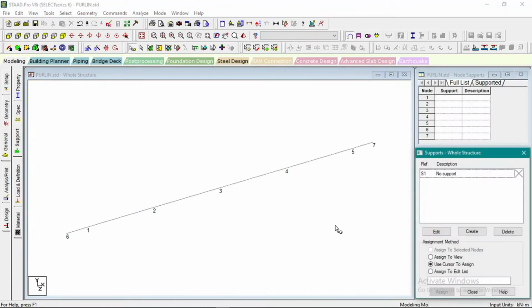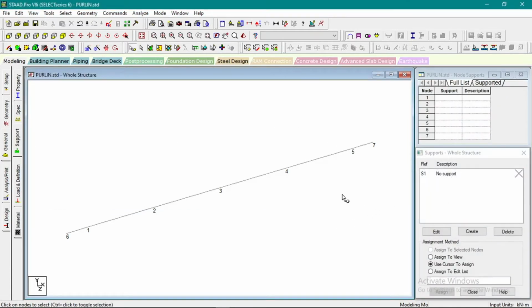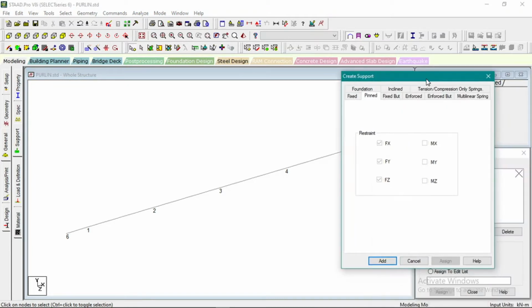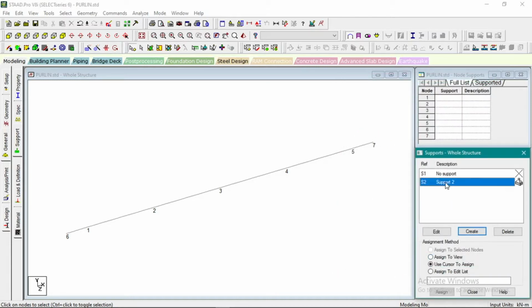Next, support. So, again, pag Purlin design, the support is the location of the trusses. So, hindi siya nakapataw. So, ang support natin diyan naman is always pinned. Okay? Again, discretion na ng designer kung gusto niya. In our case, let's go for pin support.